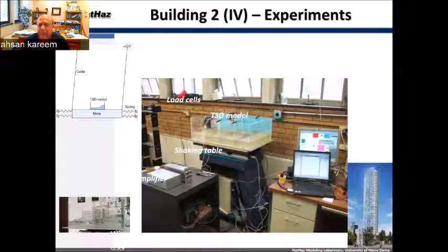We have been doing a lot of things with sloshing dampers, and what happens is that the sloshing part of the fluid is very highly nonlinear, especially when you throw in screens in there. So typically, if you want to justify this for a building, for example the one in which this tank is currently located, people have a system that uses a pendulum which represents the building, and then you put the damper in there and look at the performance. So what we had done in this particular case is what we call hardware in the loop, or these days it's called hybrid simulation.